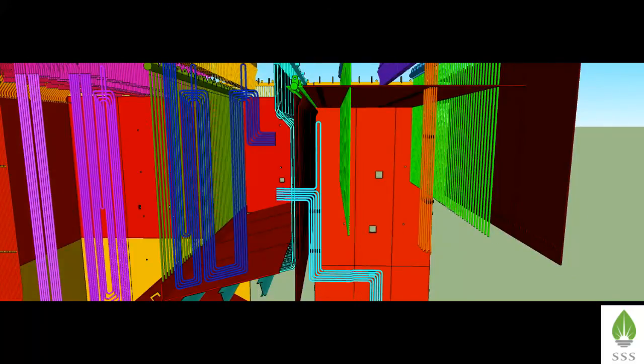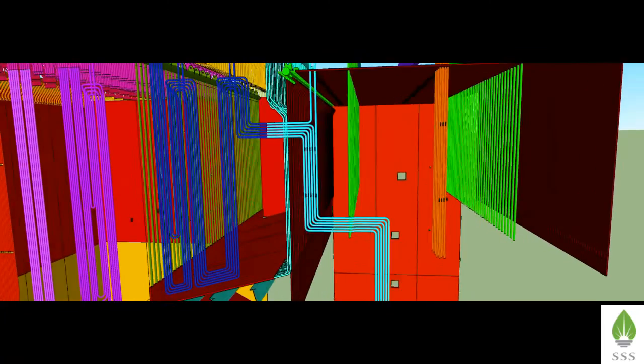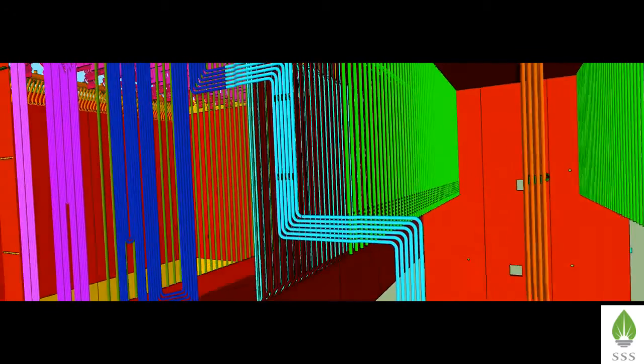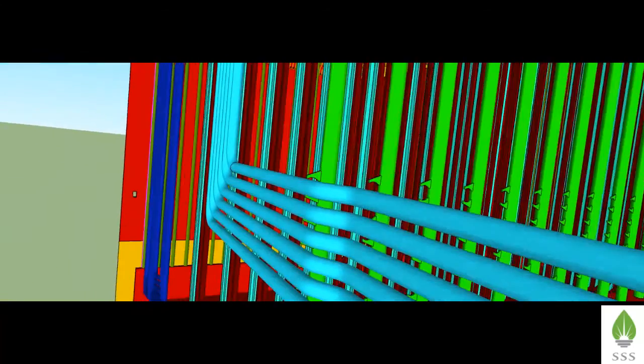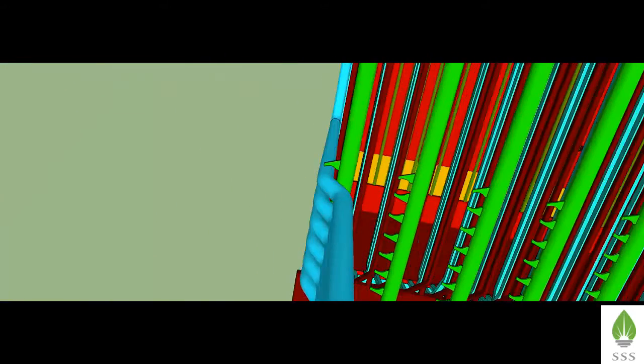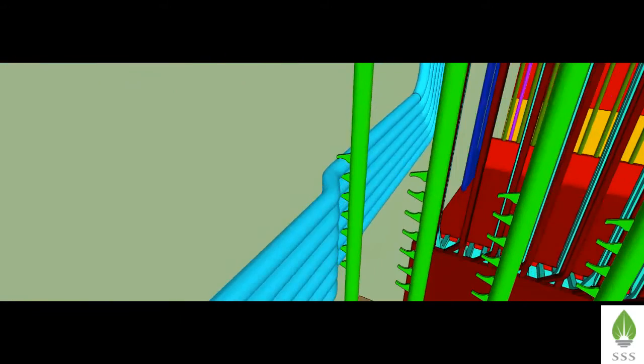The lip of the reheater crossover tube protrudes through the opening in cage roof wall. Weld these tubes with the already erected reheater tubes. The reheater crossover tubes are locked with the attachment provided on the stinger tubes.